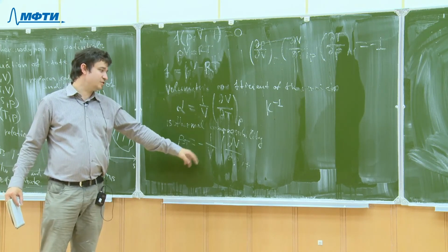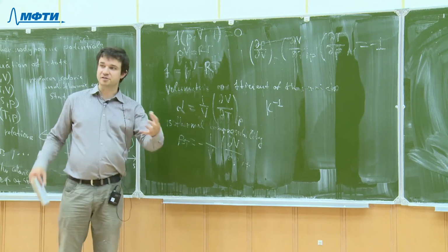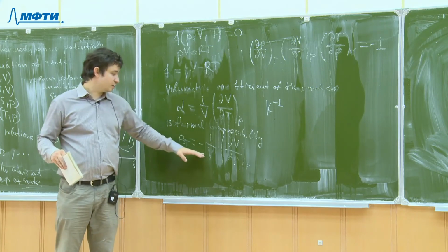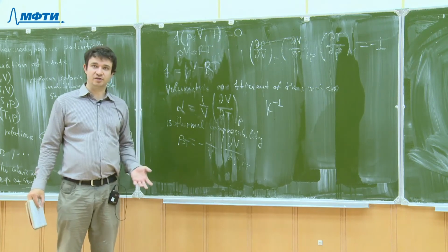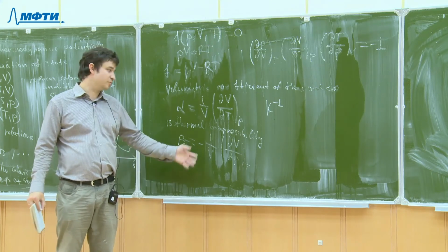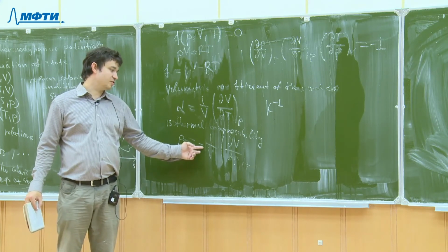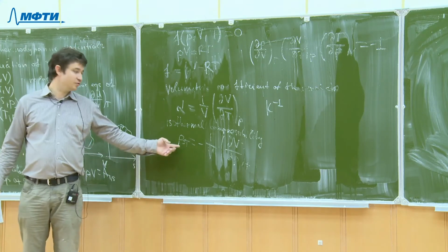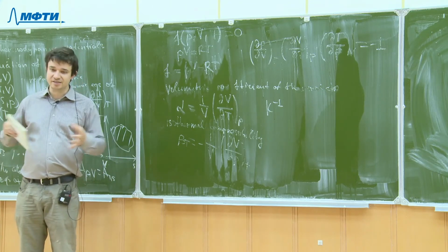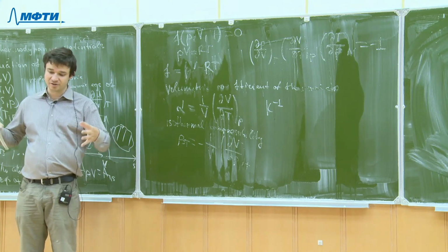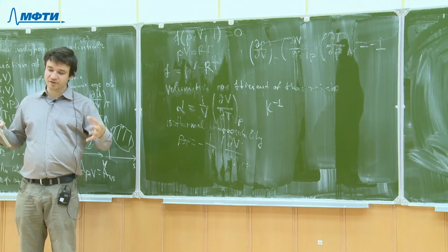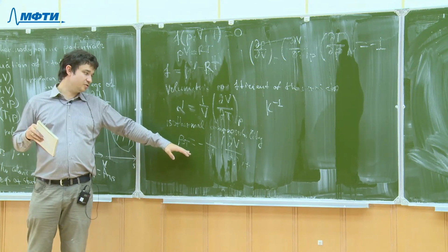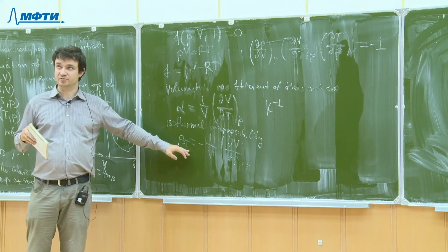But the minus here is due to the fact that if I increase the pressure, the volume decreases. That's why this derivative is negative. And since the derivative is negative, it is much more convenient to have a positively valued function, so the compressibility is obtained by multiplying by -1. So when I have greater compressibility, if I increase this beta T, that means I can compress more easily. My matter, or my gas, or liquid is more easily compressed than other matter which has a lower value of this quantity.